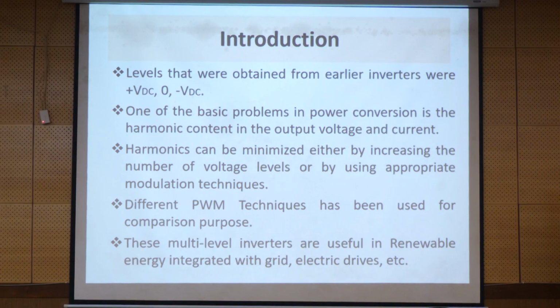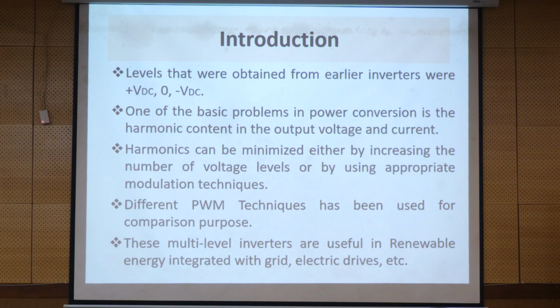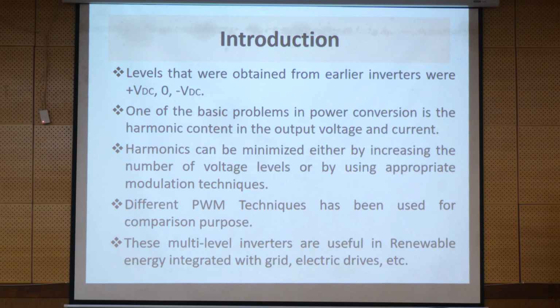It is best suited for renewable energy sources with the grid and electric drives. Distributed energy sources are connected, and even your solar photovoltaic systems are embedded with small inverter modules. Small inverter modules can be best suited with renewable energy sources with the grid and electric drives, where you want to inject power into your grid by matching the frequency and the voltage. That can be done with this kind of multi-level inverter.